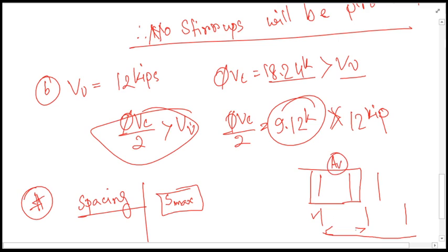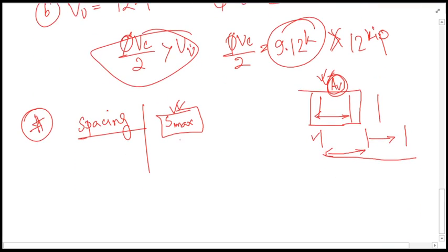As much as you give higher spacing, the area of reinforcement you are providing becomes lesser, rather than if you use the minimum spacing. As you decrease the spacing of the reinforcement, you will be increasing the area of reinforcement within a particular region. So that's why there is a guideline of S max, beyond which you cannot go, so that the minimum reinforcement is provided using the maximum spacing guidelines. So that's why you will have to follow the S max here.